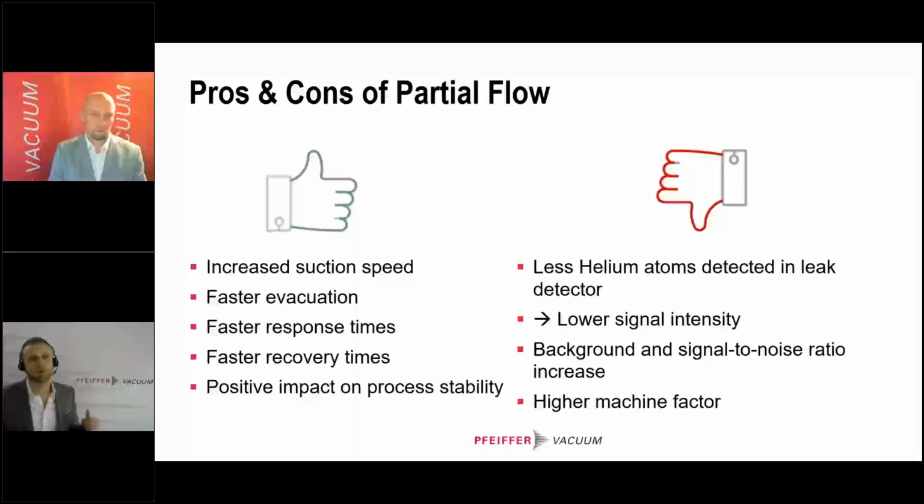and this will increase your overall suction speed. So, of course, you not only have a faster evacuation, you also have a faster response and a faster recovery time of your leak detector. And this in general has a positive impact on your process stability because you reduce risks of helium contamination, for instance.